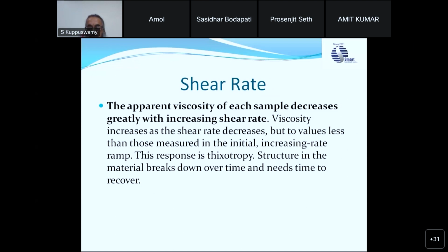So actually, shear rate and shear stress will come usually with rheometers. In viscometers, if you want shear rate and shear stress, you require cell geometry. With the regular spindles, you cannot generate the shear rate and shear stress. There will be either cone and plate geometry, or you must have the coaxial cylinder geometry to create shear rate and shear stress. With only particular small sample adapters, you will get the shear rate and shear stress.